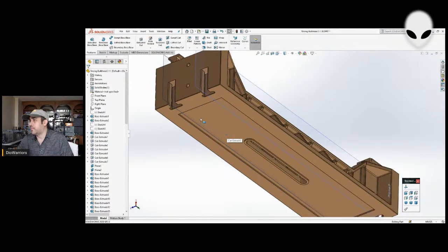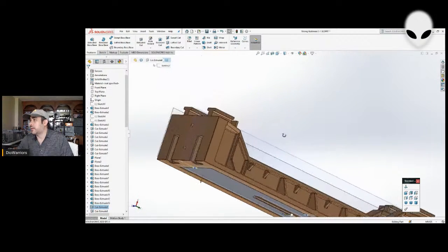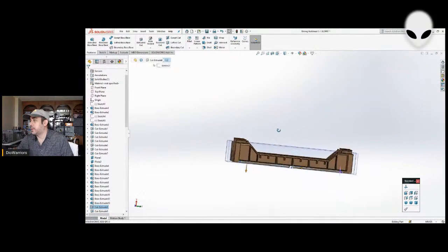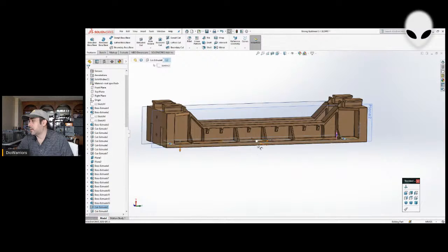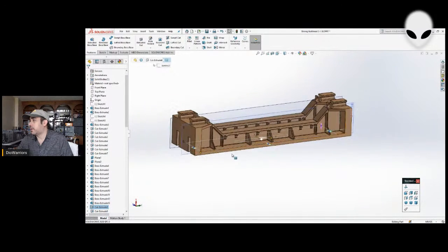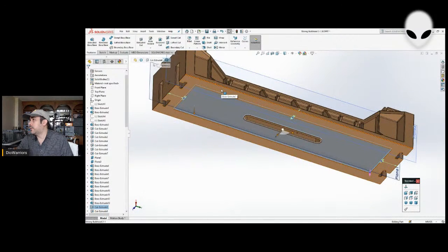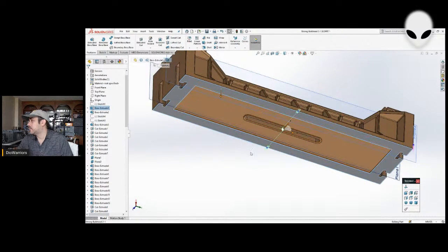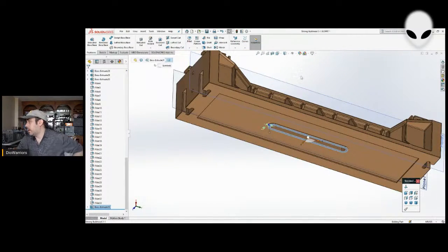So what I do sometimes is put these little cuts, like you see here, that's kind of raised off the build plate a little bit, just enough so when I put a knife or something to try to lift the item off the plate, it's only going to have a small area of resistance, this area and little areas like that. And so it's not too much surface area that's going to be resisting.